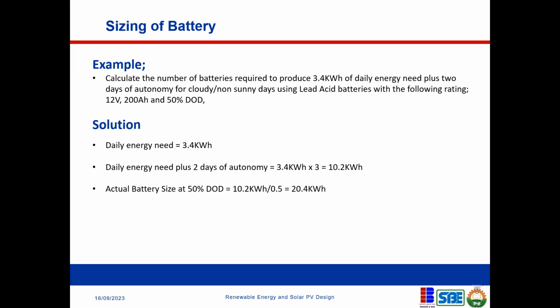So this is the battery bank. This is the size of the battery bank that we need to install using lead acid battery. If we are using lithium iron phosphate, which might have a depth of discharge of about 80%, it will be less than this. This is dependent on the battery technology you're using. But our question says we are using lead acid batteries, and our depth of discharge is 50%. So that's what we are trying to do here.